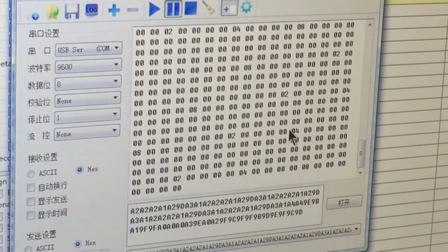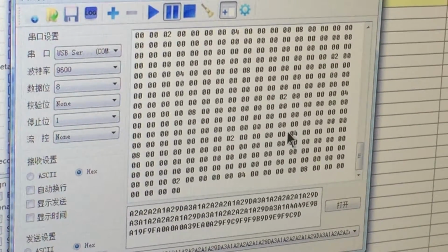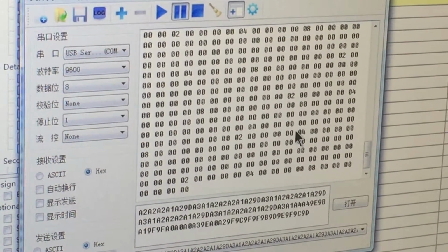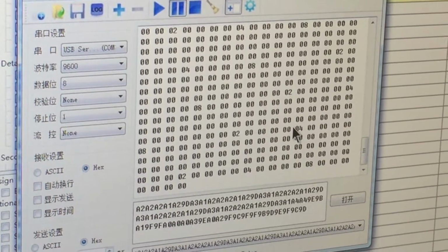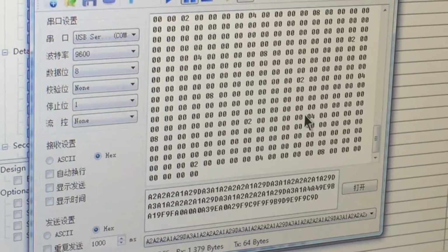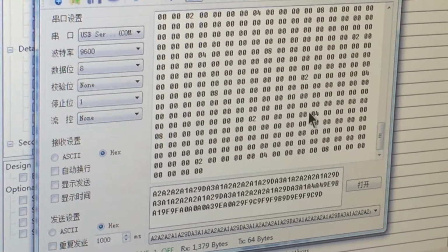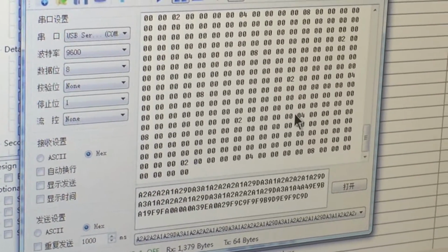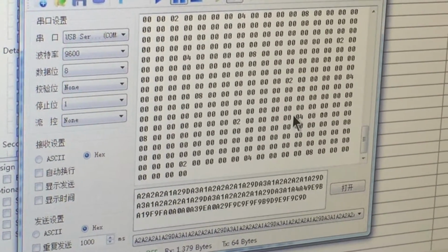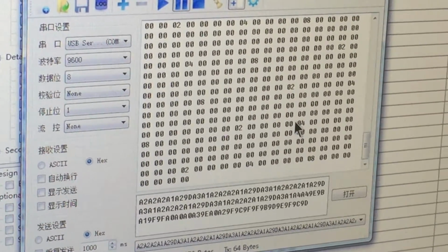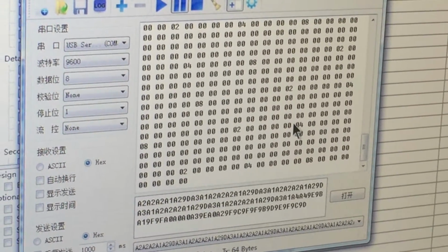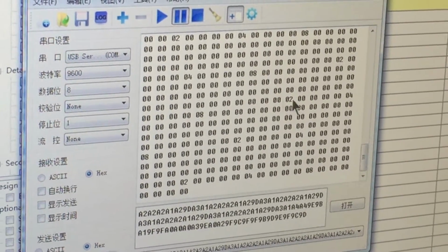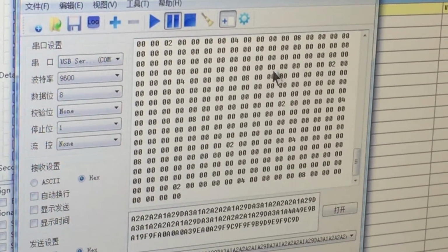So in that case, we first try to divide the 12 bits into 2 bytes, which gives us 2 redundant bits to show which one is the first one, or which one is the last one. And also we try to follow Alex's suggestion to put a multiplexer at our output to determine which one to output. However, no matter how much time we spend on debugging, the output received on the PC still makes no sense.